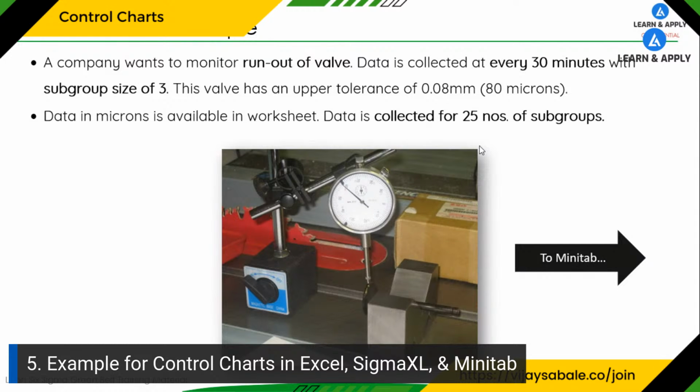Please learn it carefully. A company wants to monitor runout of the walls. Data is collected every 30 minutes with a subgroup size of 3. So here we can see we have continuous data. We are going to collect the data for runout, which is continuous, and the subgroup size is 3, which is less than 8. So we are going to use the X bar R control chart in this case.